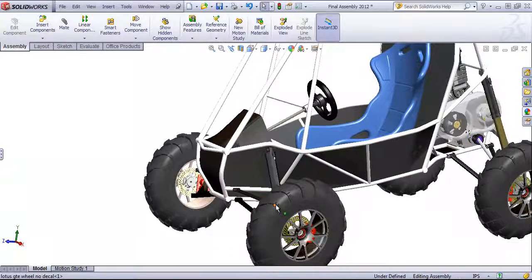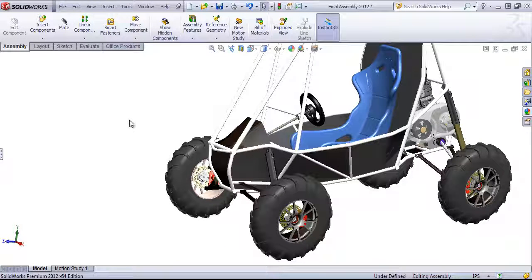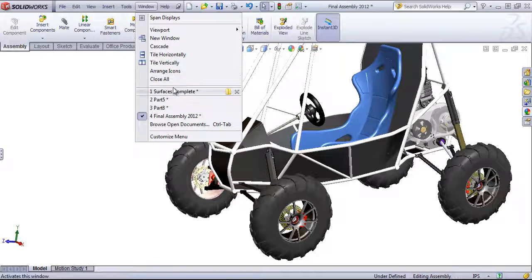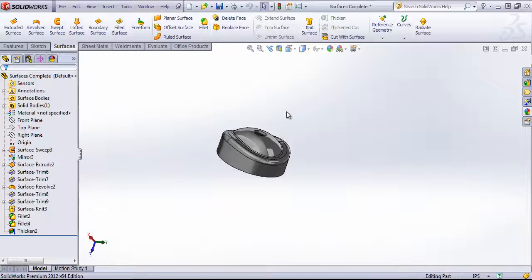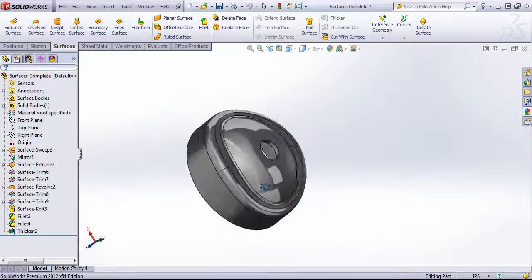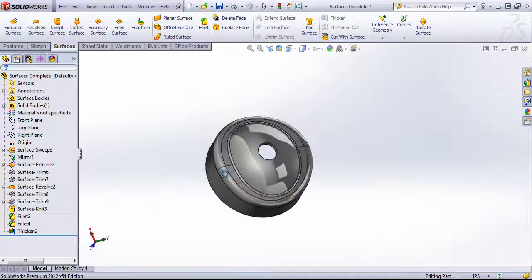While you see a solid model for these treads, I find the best method of creating treads for a tire or for similar usage is creating a surface and then using a series of either thicken features or thicken cuts to create the treads. In one of the subsequent lessons, I'll be covering how to create a part like this.